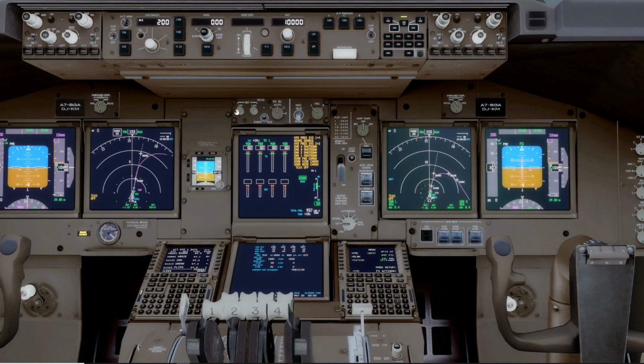We'll come over here and check the ICAS. Brightness display is as desired. EIU auto selector in auto. Heading reference switch in normal, FMC in left. Alternate flaps are off. Alternate flap arm switch is off. Alternate gear extend switch is guard closed. No indications. Landing gear lever down, and the auto brakes, we can go to RTO.